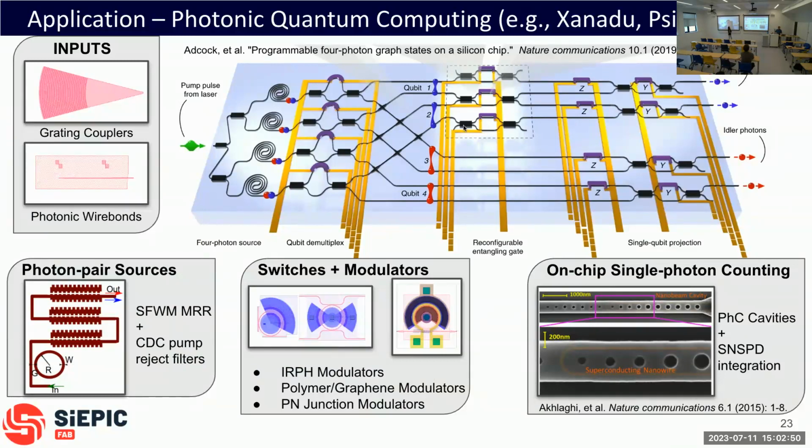Okay. And so each one of these interferometers where you split the light in half and recombine it, if you have 2 control signals, you can essentially rotate the photon anywhere in the sphere. Okay. So imagine if you come in with a photon on the top, the output photon can be any linear combination of these 2 outputs. Okay. And so by making this mesh, you can create any unitary matrix by just controlling the knobs.